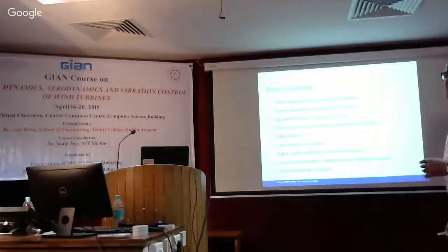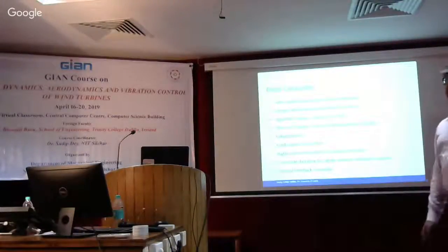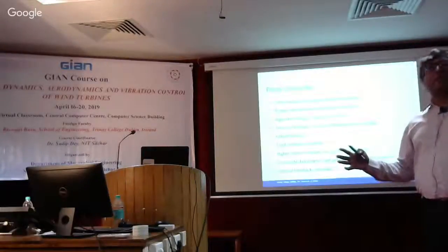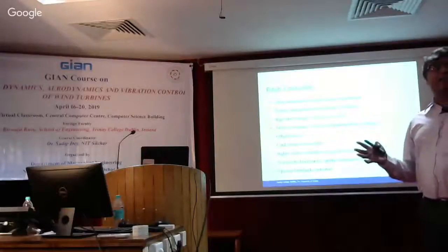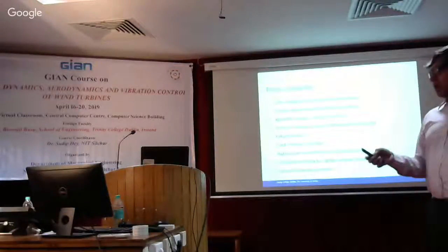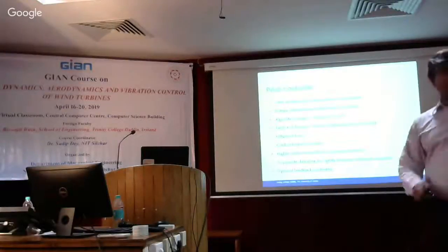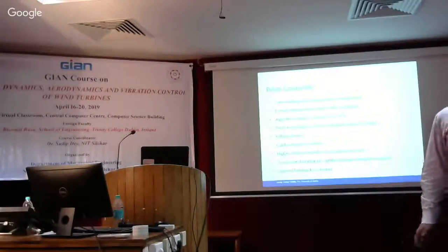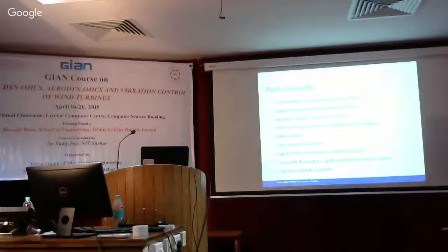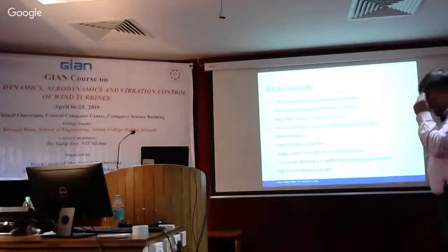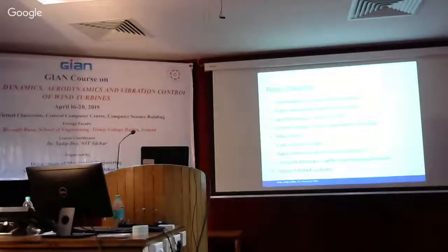And then as the vibration controllers came, one of the functions of the pitch was also to influence the load, in fact, as we'll see. And they were doing that between 2002 and 2007, when pitch controllers were started and being used in the industry. And then subsequently, the vibration controller took off. So the load reduction part was then given to the vibration control hardware, and these two, pitch control and torque control, were mainly introduced for algorithms. But you can of course also reduce load by using pitch controllers, because if you change the angle of the blade, that will have an impact on the load. We have seen that in calculations.